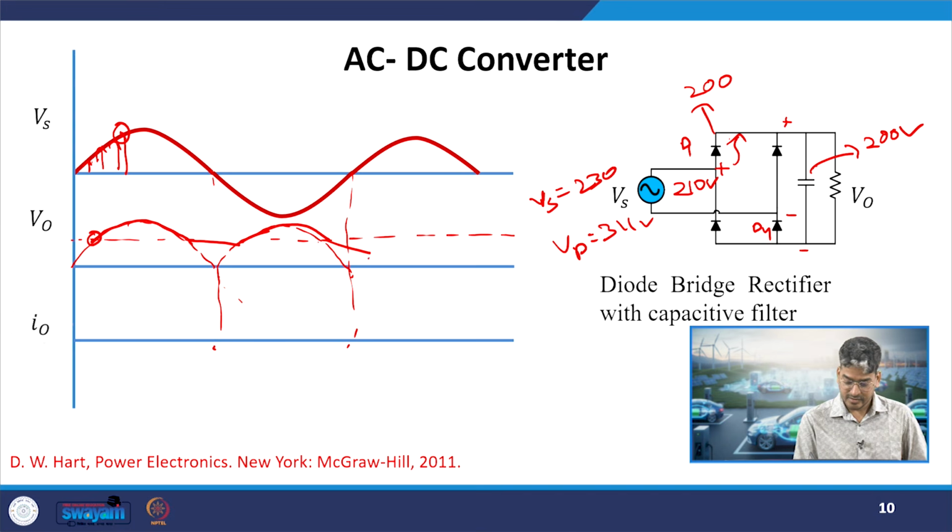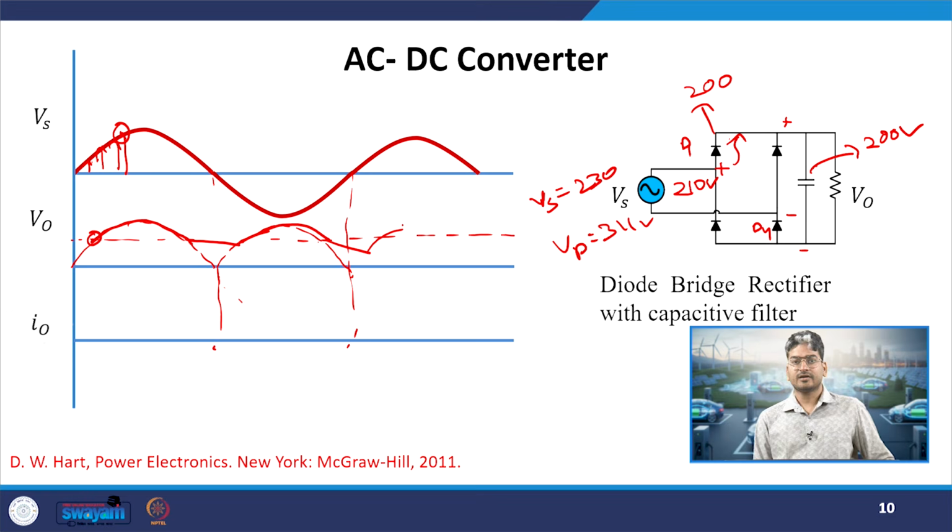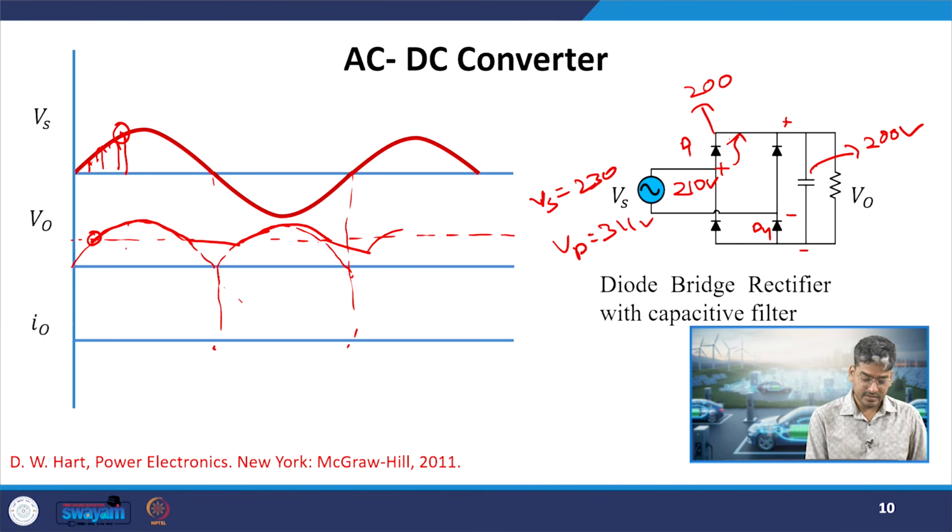Then again over here it will start from this point and continue the conduction. Okay. So, what has happened now? As my capacitor voltage is increasing, the time given for my diodes to conduct will be decreasing, because it will wait till it gets closer and closer to 90 degrees. The more the voltage, the more time it will wait till it becomes positive biased and starts conducting.